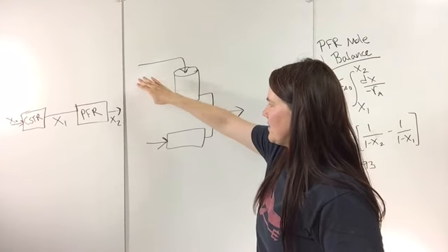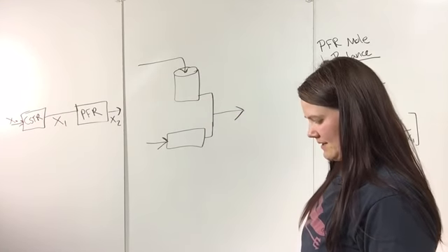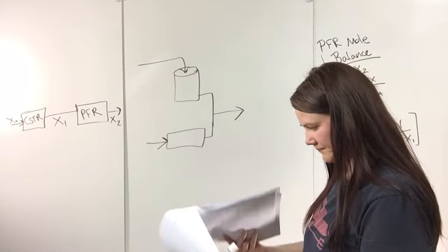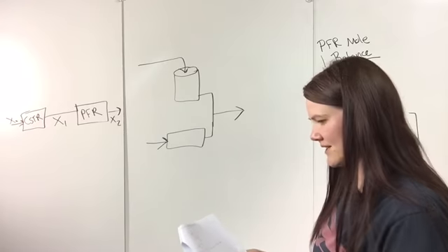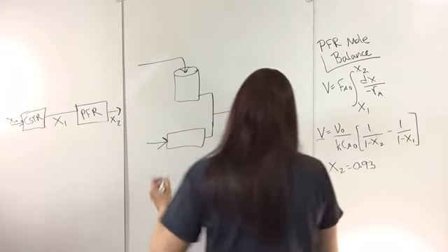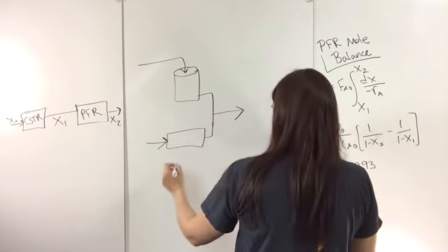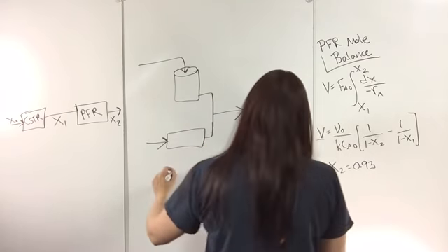So the flow rate, instead of 10, what was it? Instead of 10 dm cubed per minute, it would be 5 dm cubed per minute. And so you would go through and calculate x for both of these using that different flow rate. And then the overall conversion is just the average. So x is equal to x CSTR plus x PFR over 2.